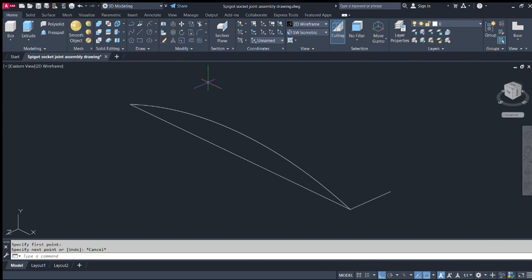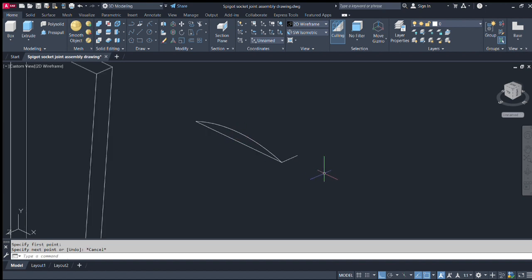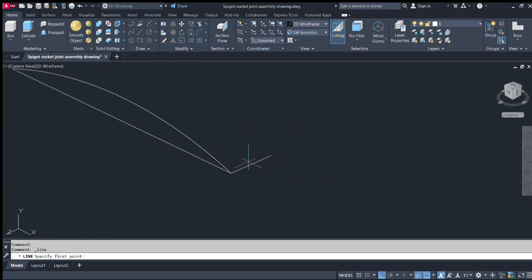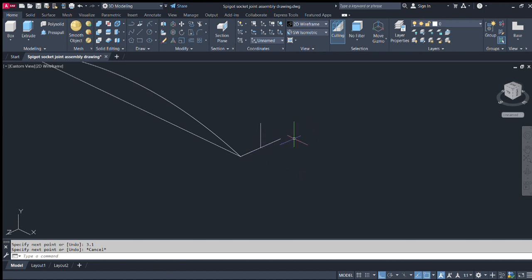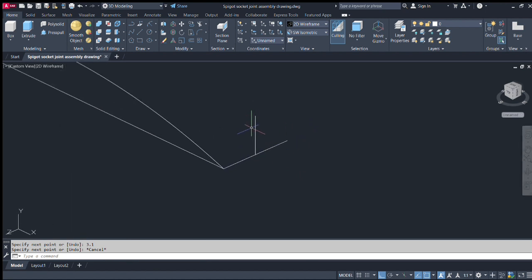In order to see what should be the length of that particular edge, we will check the length here. The maximum length of this particular arc from its base is 2.97. So we will take 0.1 mm extra, just an increment of 0.1 mm. So from here I will give the length as 3.1. It was almost 3, 2.97, so I will take 3.1 here and press enter, from its midpoint, not on the ends, and it should come above.